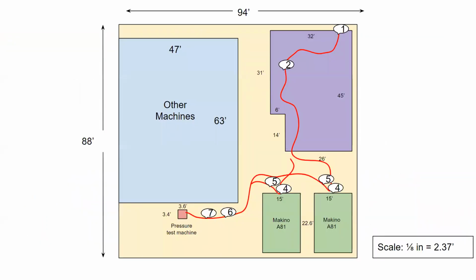The second spaghetti diagram shows our first alternative and the new layout condensed into the space available within the same building. The CNC machines will be situated where the part exits from the die casting machine and will follow the new path shown for the preceding steps in the cycle. The travel distance is drastically reduced along with worker fatigue.